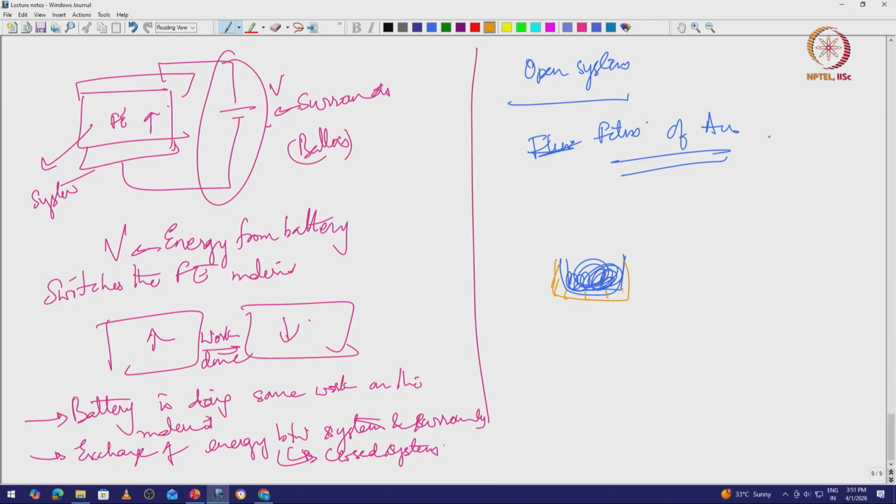So I have a crucible of gold, with gold inside, and I am heating it with some coils. I am either resistively heating it or heating it with electrons, in what is called E-beam evaporation. Once I heat it, the solid gold sublimates into vapor gold. This solid gold is bulk gold, it is not in the shape that I want.